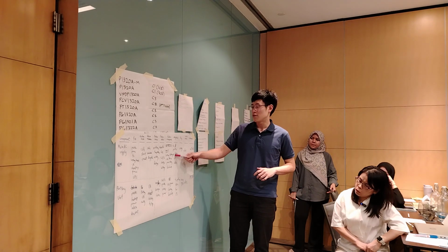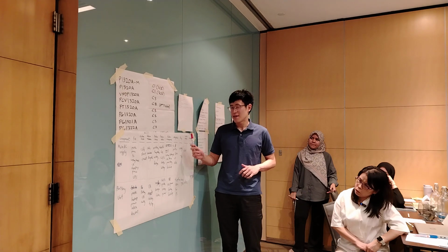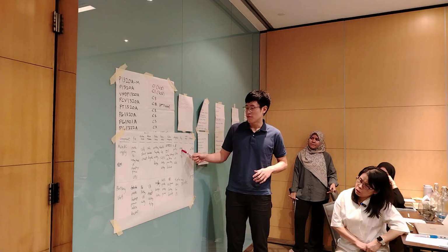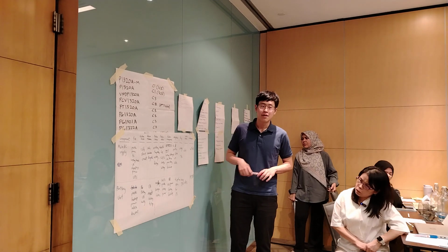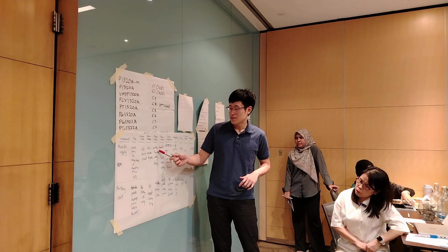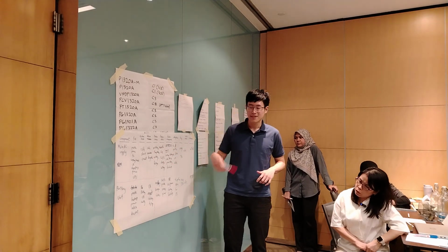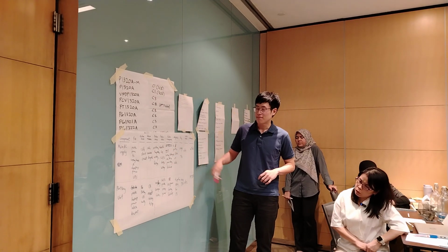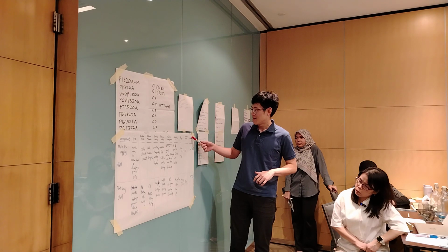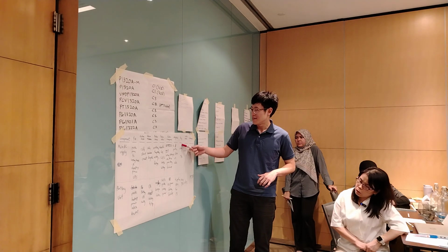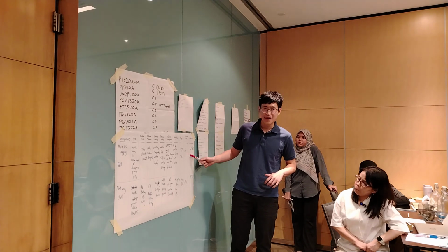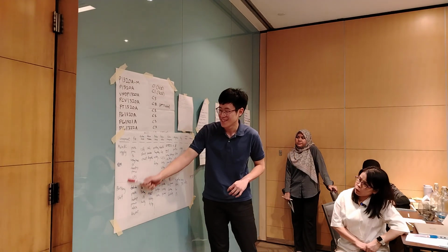Starting from 20 years, we will perform the CBM every 3 TA, so every 7 to 10 years. Basically, we want to get the insulation resistance of the cable, as well as other technical parameters. The work center is electrical. The reference for the condition-based monitoring is the mean time between failure. And trust us, we are the engineers.